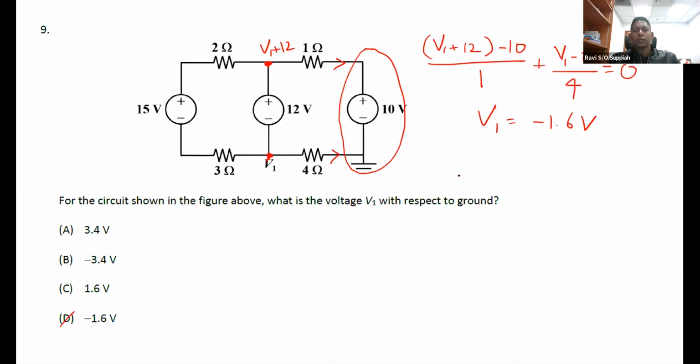Yeah, so this ground is not the same as your AC ground. In the AC supply, when you have the ground, that ground is really ground. Because when your appliance gets damaged, say there's a short circuit in your water heater or something like that, then that spike in the current would be channeled to the ground. That means the electrical cable in your building will transfer that current to the ground. So that is the protection mechanism in the AC supply. Correct. In a DC supply context, the ground is generally the negative.